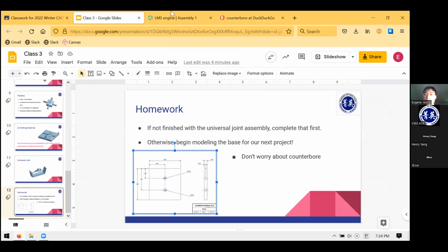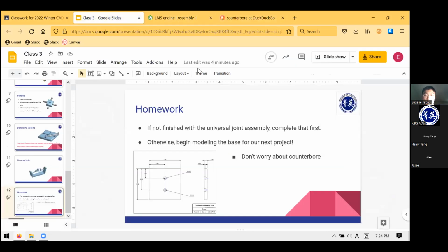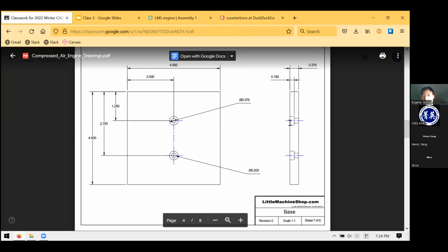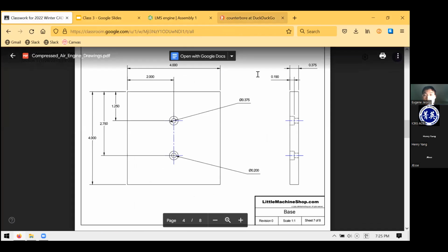And so these part drawings are all going to have some kind of accommodation for usually bolts. So in this first drawing, what you'll see is that these holes are counterbored. And that means that there's a larger diameter hole that goes partially through the depth of the hole, and then the rest of the hole is just the nominal diameter, which is specified.